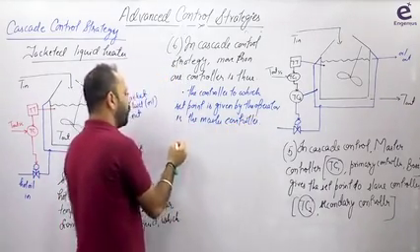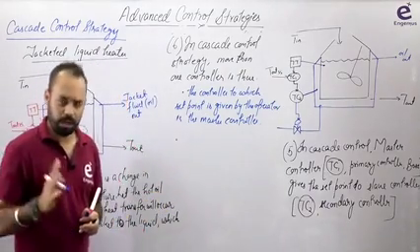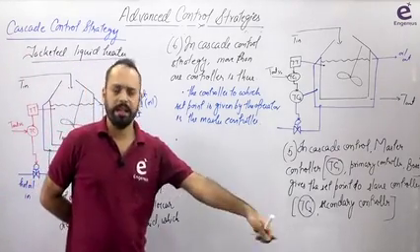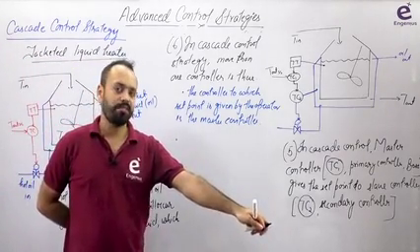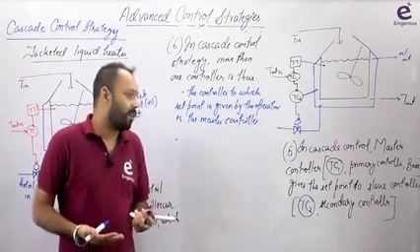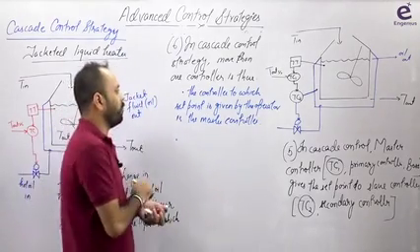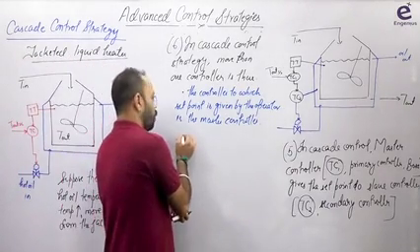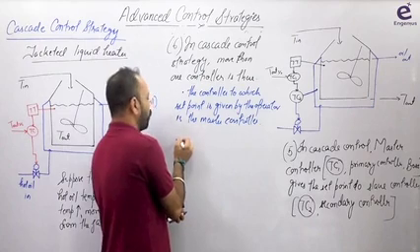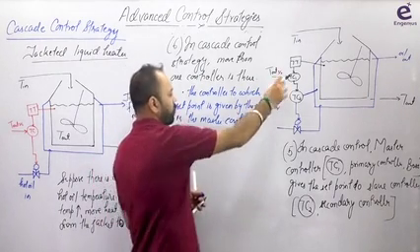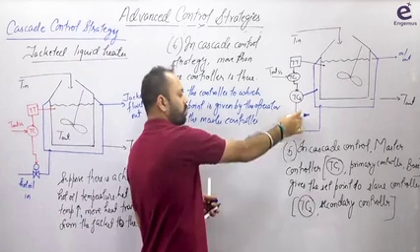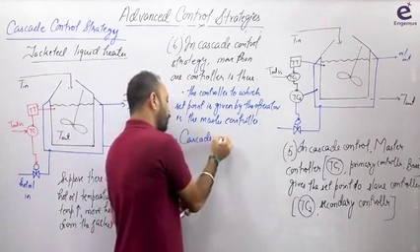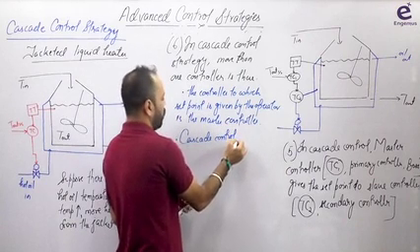Right? Now you may ask, sir, what will happen if there are three controllers? If there are three controllers, the controller to which the set point is given by the operator is master and all of the rest are slaves. But what will the slave be? That's why I'm saying that cascade control is like a hierarchy. Let us write this point. If we discuss everything at once we will get confused. Okay, what else can we write? In cascade, suppose this is the senior, this is the junior, whoever comes below is the junior, whoever comes below that is the junior, right? So a cascade control can be thought of.